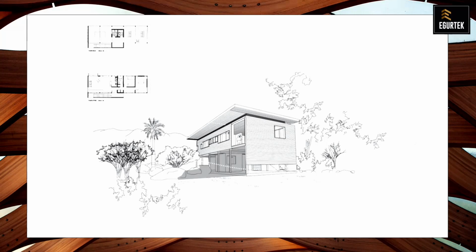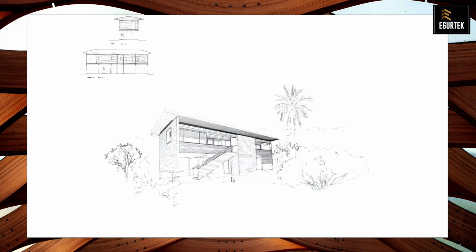And here, well, this is another picture where you can see the shade that is produced, and then the soil has lots of thorny vegetation and lots of rocks. And instead of using these supports where the wood is overlapping the foundations, what we used was a layer of reinforced concrete that also provides rigidity for the structure.